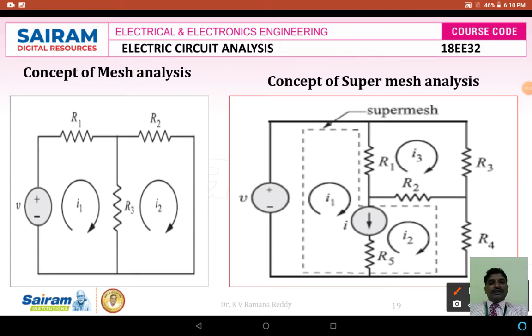If you look at this figure, in this circuit diagram there are three loops. We are analyzing the three currents as I1 in loop 1, I2 in loop 2 and I3 in loop 3. If you compare the concept of mesh analysis and super mesh analysis, here we note one important thing, that a current source is located between the boundaries of loop 1 and loop 2. Wherever a current source is located between the boundaries of loop 1 and loop 2, it is difficult to analyze the circuit.